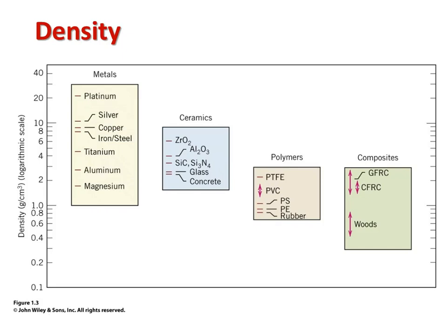Ceramics are definitely less dense, and that's mainly because you have lower atomic weight components. There's a lot of oxygen, nitrogen, carbon present in, give or take, 50 atomic percent. That tends to be the origin of the lower density there, but they're still higher than polymers. Polymers' lower density comes both from the fact that it's lighter elements and it is a less dense structure in general. The polymer molecules cannot pack as closely as a ceramic or a metal.